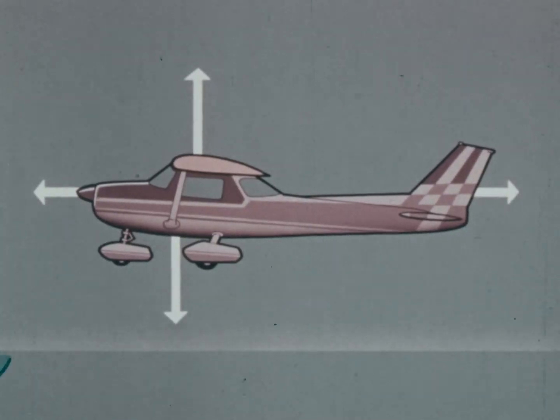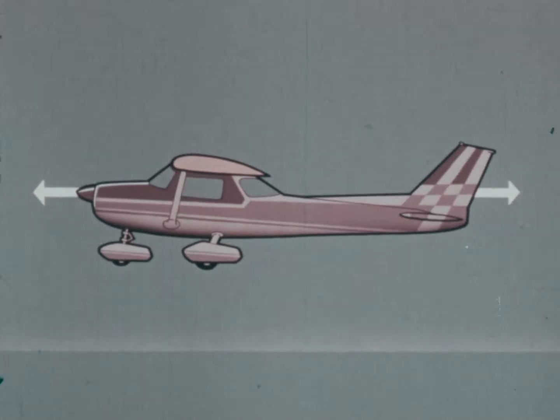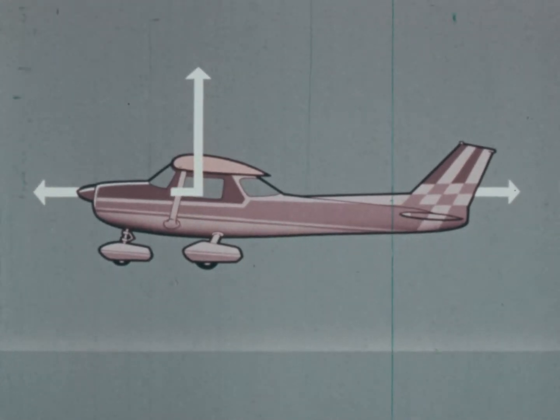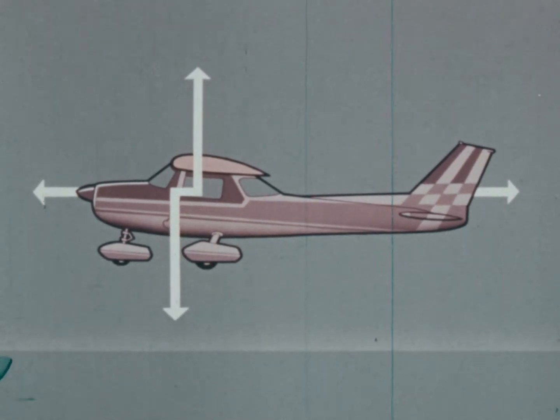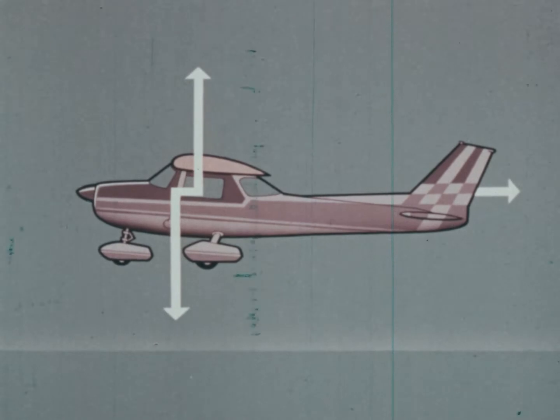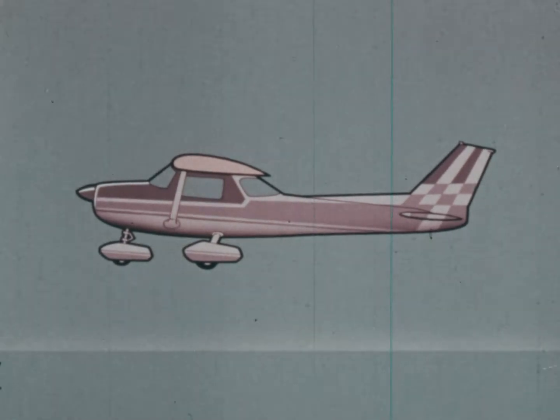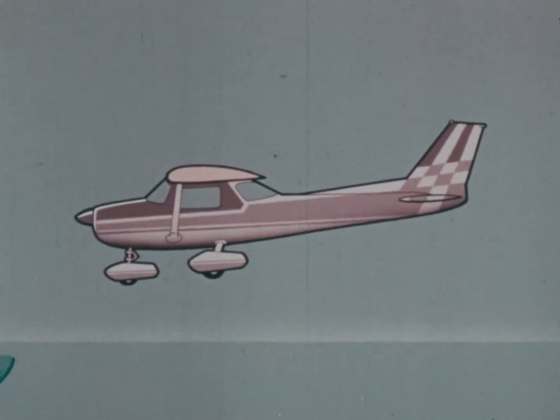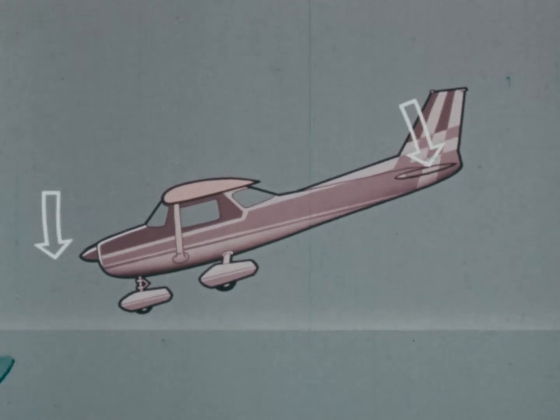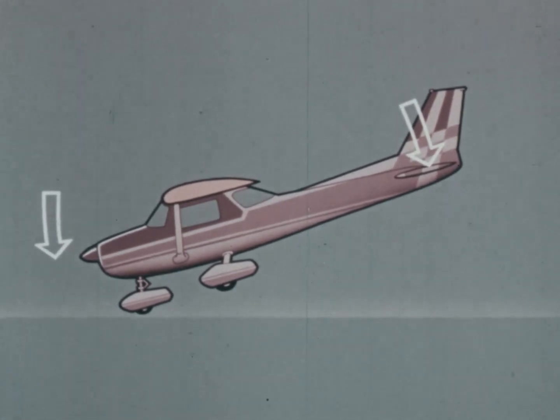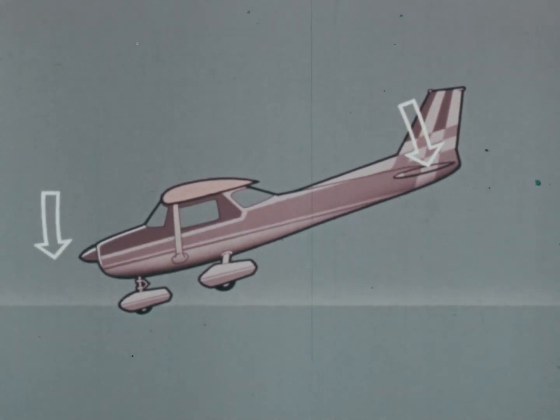To begin with, the four forces seldom act from the same point on the airplane. Weight is normally arranged to act from a point ahead of lift, in such a way as to create a nose-down moment around the lateral axis, so that when power is reduced, the airplane will pitch nose down. As it does so, the download on the rising tailplane will keep the airplane in a stable descent at a stable speed and under normal control.